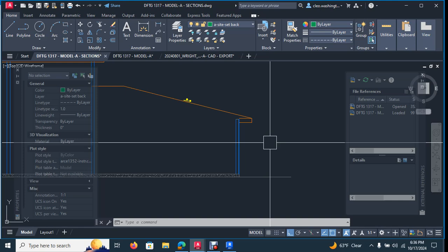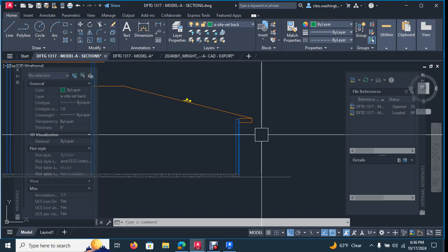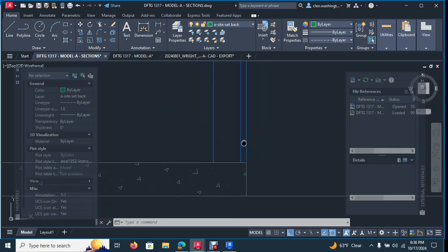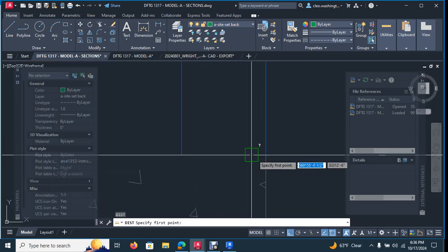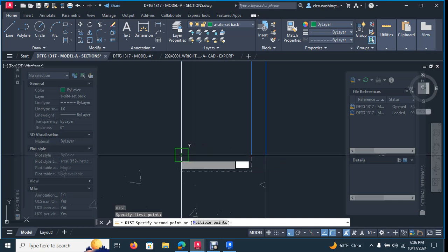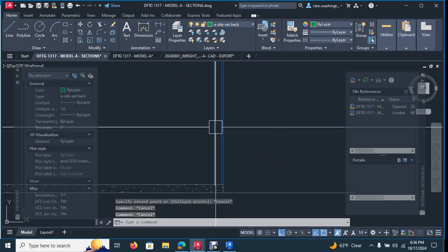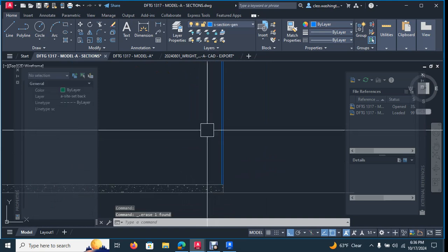Once the sections are drawn, you go back to your main AutoCAD file and you import your sections in, or you X-reference your sections in, and then you go and make sure you have all of your interior and exterior walls drawn in on the floor plan at the right dimension, okay? So right now, if we do a DI, this guy's drawn in at 5 inches when it really needs to be 5.5, right? Because it's a 6-inch wall stud.